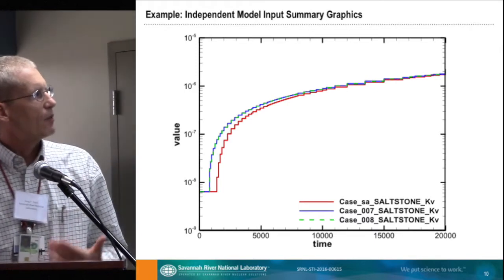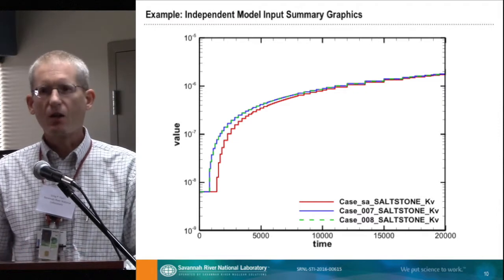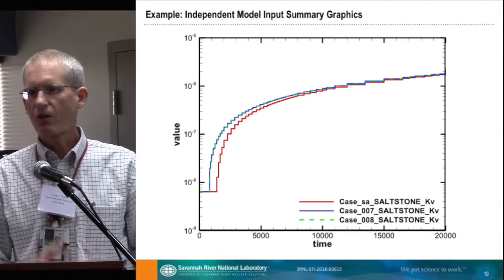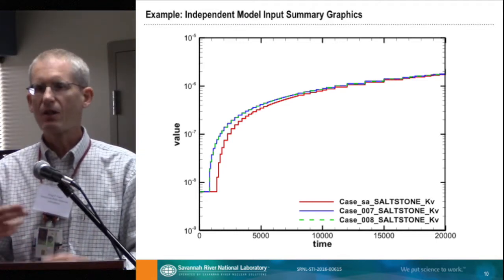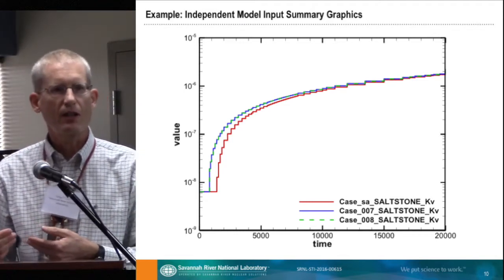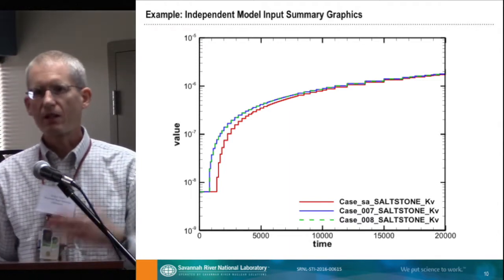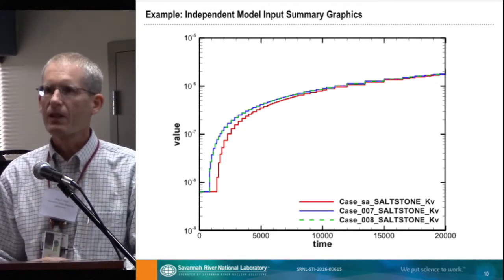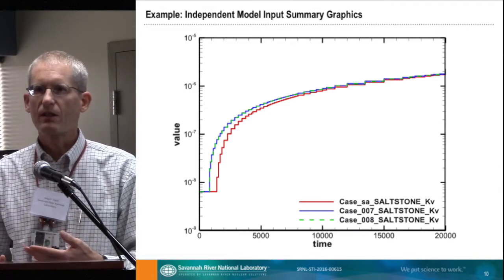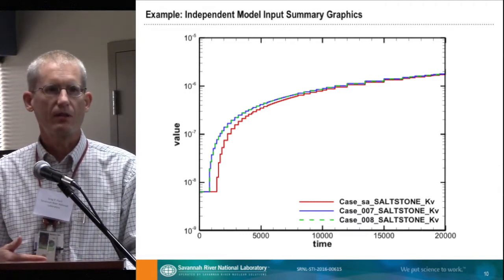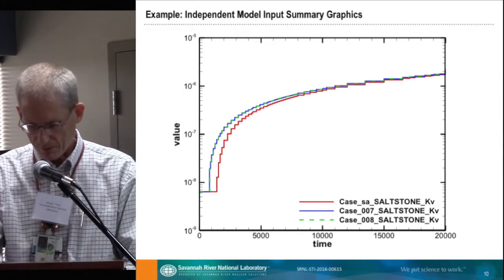So what we've created is what I would call a QC tool that doesn't know anything about how a PORFLOW input deck is created. It just goes directly to the PORFLOW input deck, extracts the most important things out of the input deck, and creates summary plots and tables so that you can very quickly, visually or in table form, verify that all the property changes through time are consistent with your concept or your high level specification for that scenario or modeling case.